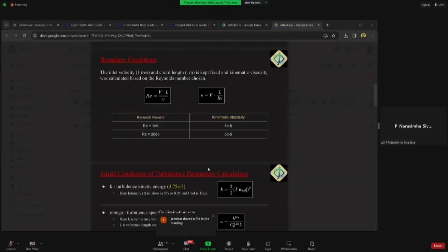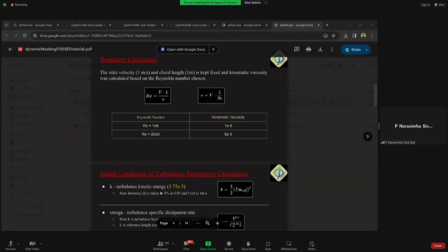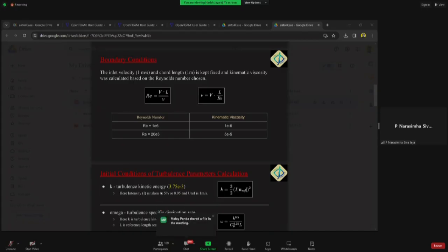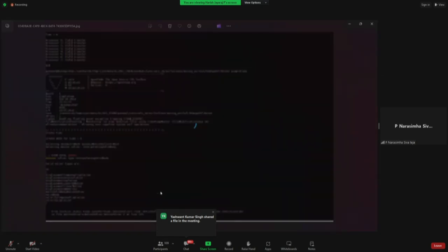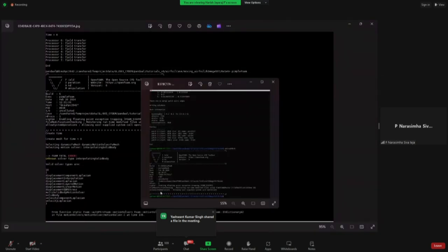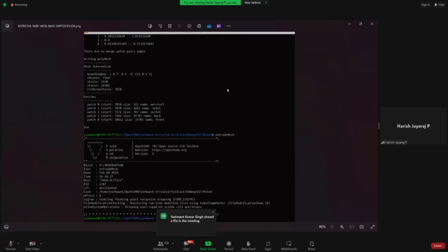We are getting an error whenever we are running this in parallel, like no convergence criteria found. And finally, it says invoking mpirun causes Open MPI to kill all MPI processes. Then maybe you just selected the wrong number of processes. That could be a reason.